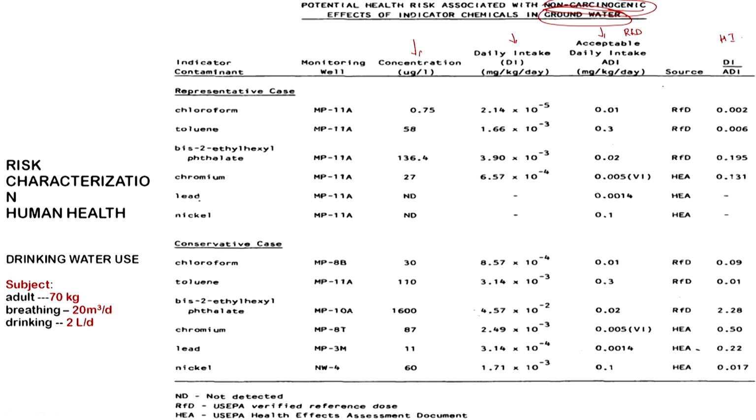Some is, I think, hazard quotient. How do I calculate that? It is daily intake divided by the reference dose or the acceptable daily intake, right. Usually the threshold is 1. If the sum of all the hazard index is greater than 1, that means that I am taking way too much of the toxic compound, and I need to look at the relevant remedial